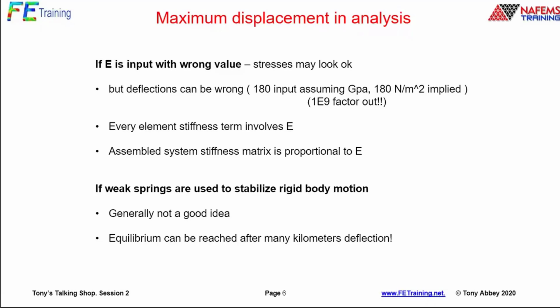Where we have rigid body motions, the solver detects that, and rather than giving a hard diagnostic saying, tough luck, I can't solve this because we've got rigid body motions, you need to do some debugging, it says, don't worry, I'll fix it up for you, and puts these system springs in, distributed throughout, automatically, so you don't know where they are. And then we can reach equilibrium because we've got these springs in.